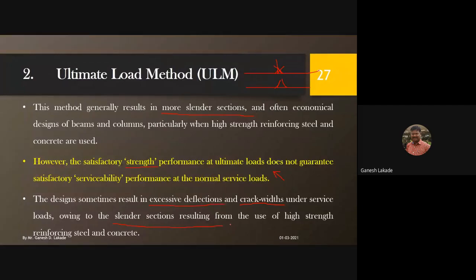That means how the structure actually behaves, what the maximum deflection will be, or what the limited deflections should be. These kinds of factors were not considered. And these factors have been considered again, sorry, in addition, and that is what we call the limit state method. So in the limit state method we are considering different kinds of limit states, and one of them is the limit state of deflection, and such different limit states exist, and that's why we call that method the limit state method.